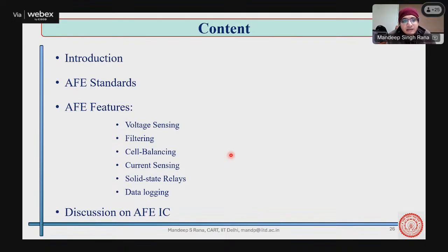So basically, voltage sensing has these many basic things. First, just to look at the voltage, we need to have several arrangements. Let's say you have some sort of resistor divider, then you have your own differential op amp. Then the next thing is you need to have a filter. After the filter you have a multiplexed ADC. There also you need to have a lot of data coming in.